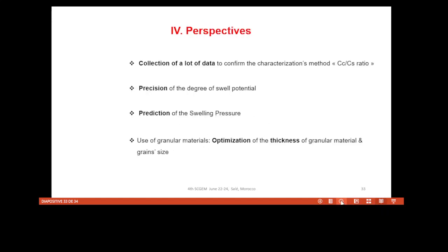As forthcoming development, we need to collect a lot of data to confirm the characterization method we suggested. We also need a precise determination of the degree of swell potential or the prediction of the swelling pressure, and to confirm the use of granular materials, we need to optimize the thickness of the granular material layer that we can place as an interface between the expansive soil and the foundation.